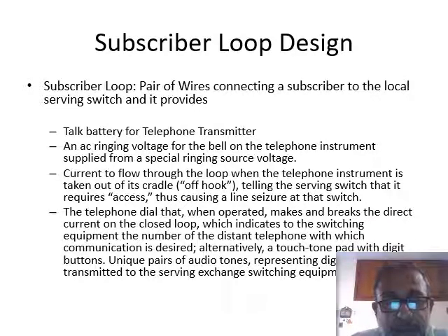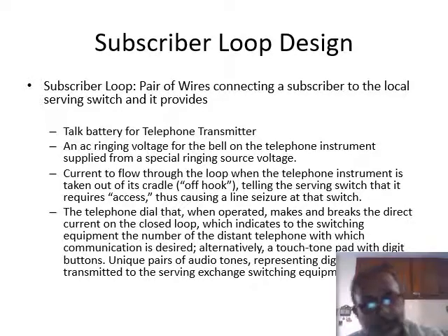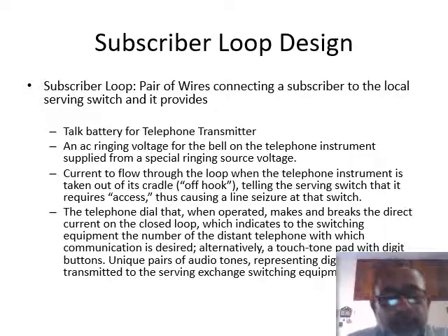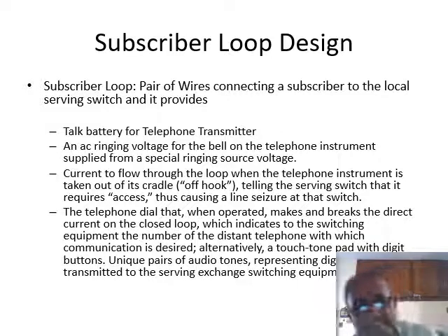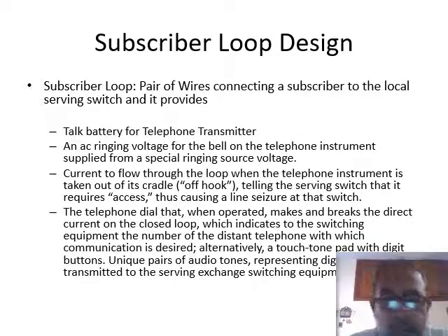Similarly, we have the capacity of dialing 10 different numbers from 0, 1, 2, 3 up to 9 in that case. While in a DTMF system, which is also called a tone system, it is normally made in the form of 12 buttons, which are placed in 4 by 3 format, because there are 4 rows and 3 columns.